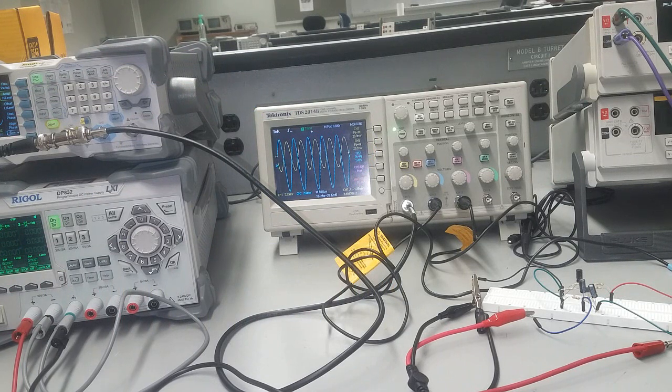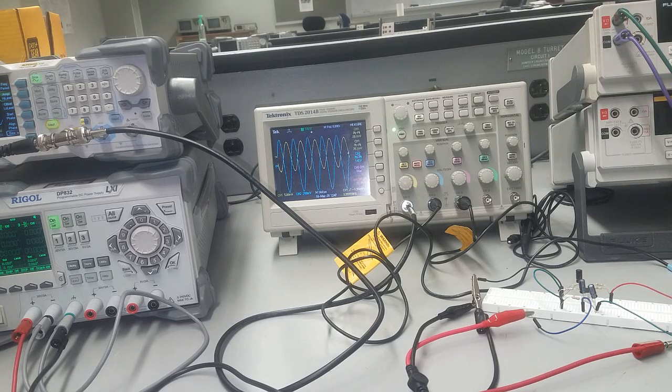There are two possibilities to lower the gain. One of them is to reduce the current, and the way you reduce the current is by making the resistor at the source bigger. This will lower the current going through the drain, and that will make GM smaller, because GM is proportional to the square root of the current. So if I double the resistor, I will cut the current by half, and that will give me roughly a 70% drop in GM, and that's proportional to the gain.